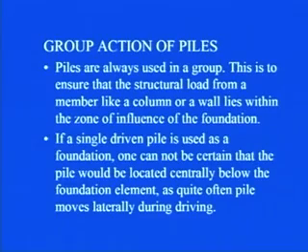So, in case, let us say, only one pile is there below the foundation, in that case the center of gravity of the pile must coincide with the load which is coming from the superstructure. In case they are not matching, then there will be a problem, because some eccentricity will be there and that will cause a moment, which will result in bending of the pile, and so the failure of the same. Therefore, to avoid this kind of situation, a single pile is never provided below a foundation, because usually what happens is, while installing the pile, it moves laterally, it is never vertical.